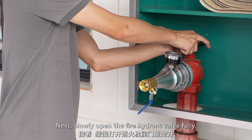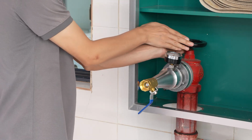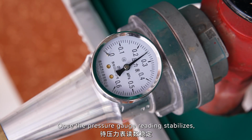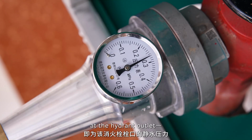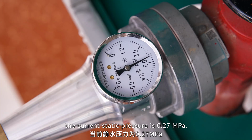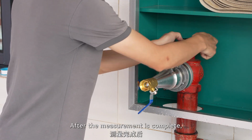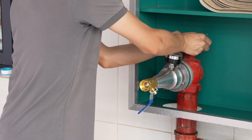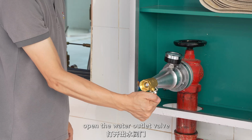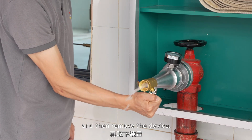Next, slowly open the fire hydrant valve fully. Once the pressure gauge reading stabilizes, the displayed value represents the static water pressure at the hydrant outlet. The current static pressure is 0.27 megapascal. Finally, disassemble the setup. After the measurement is complete, close the fire hydrant valve. Loosen the pressure gauge connection. Open the water outlet valve to release the pressure from the test device, and then remove the device.